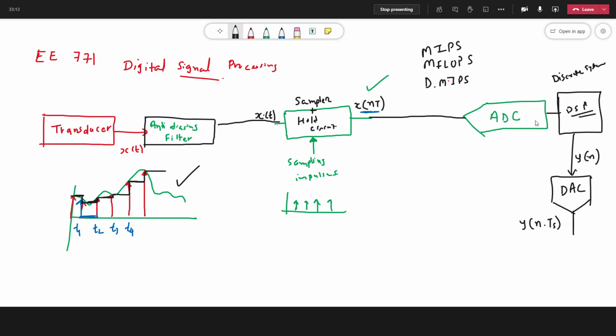Then I may need to suppress several harmonic using the digital filter. So algorithm, that digital filter will be implemented or will require to be implemented on the platform of DSP processor. Now, as this is a music signal, your application may also need to convert it back into the analog, because you may also need to hear this signal again.